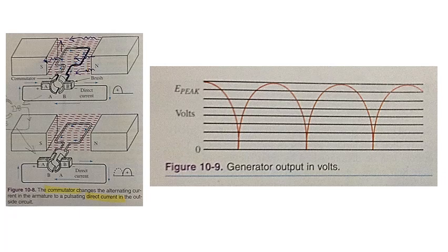Follow the action in figure 10-8, the figure from before. Rewind if needed. Brush A is in contact with commutator section A, and brush B is in contact with commutator section B. The first induced wave of current flows through the armature out of brush B, around the external circuit into brush A, completing the circuit.